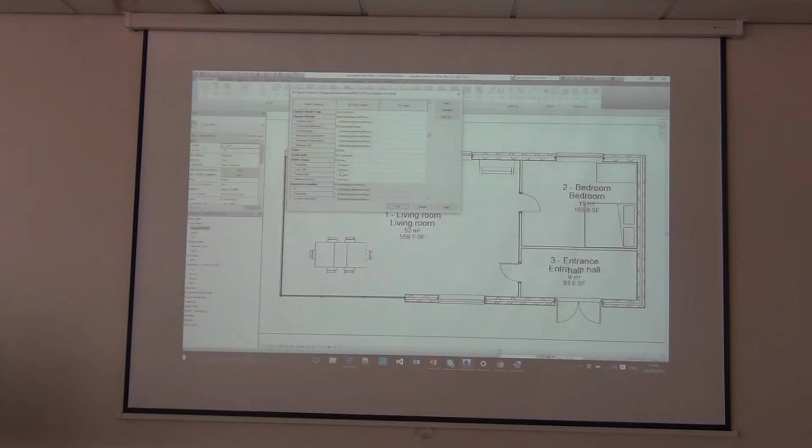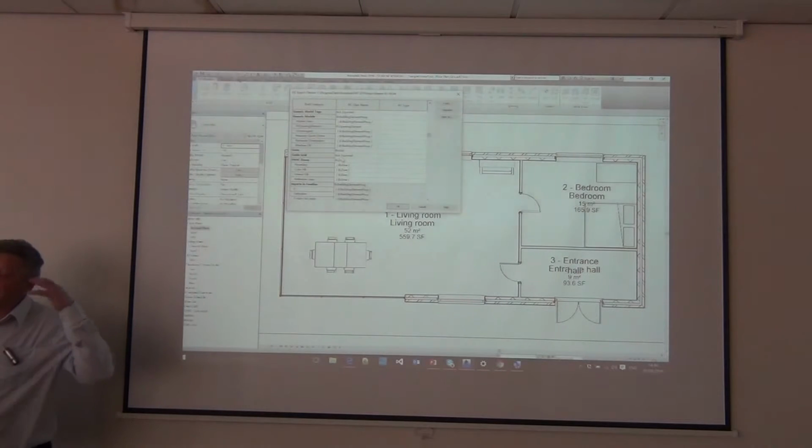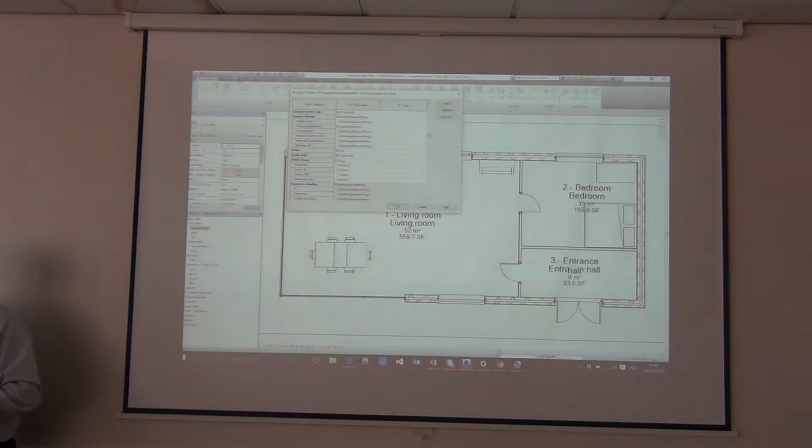So each of the things in Revit has a counterpart in IFC. Revit is actually built on IFC. Okay, so the conceptual model in Revit, that's not strictly true. The design of Revit is the same as IFC in terms of the object model underneath. So it's quite easy to see how things map between them. When you use platforms like ArchiCAD, it becomes a little bit more difficult because it wasn't designed on that kind of basis from day one.